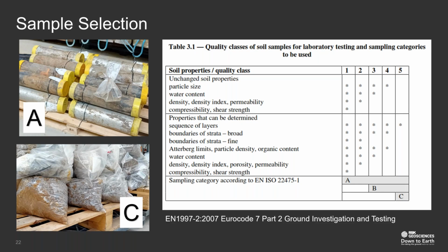During the site investigation, it's really important to collect a variety of samples to enable the soils to be classified. Generally, the testing is constrained by budgets. However, the more information you can obtain, the easier it will be to refine your ground model and review and remove those data gaps from the conceptual site model.